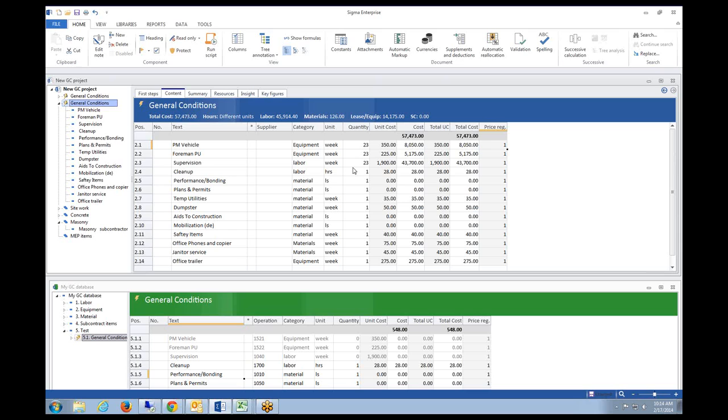As an example, and I'm just taking this next step, if I wanted to build an assembly, just say for concrete sidewalks or concrete curbs, doesn't make a difference, I could have a pop-up say, how many linear feet of curb and gutter is there? And I could say 1,100 linear feet, right? Then the next prompt, production rate, I could just say 50 feet an hour, or something like that. It would then calculate my labor hours as well. Exactly, based on the assemblies that you will have underneath.